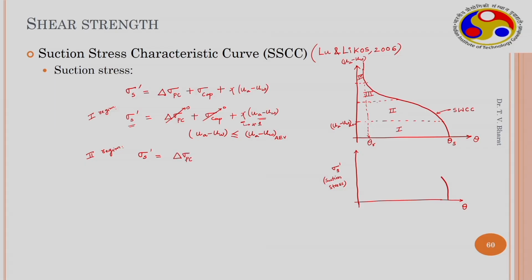If the soil desaturates quickly, the van der Waals forces remain nearly constant, but the repulsive pressures within the soil mass start decreasing. So, this is insignificant, close to 0, but the capillary forces are significantly higher and start increasing.